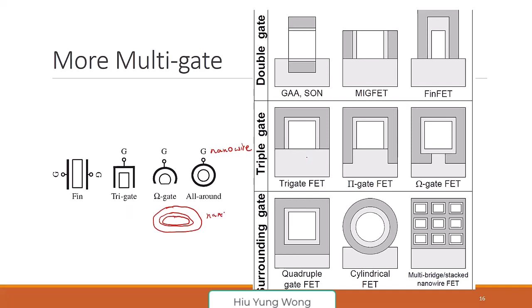And the overall performance will be better than nanowire. Of course, you're right, in terms of control, nanowire is better than nanosheet, right? Nanosheet, if you make it extreme, is just like a double gate fin. So you find the middle that gives you the best results.